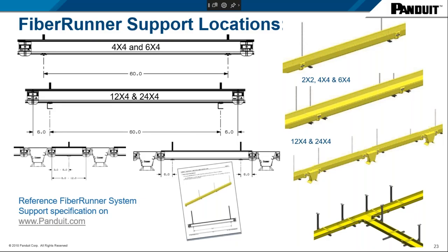And when you have a joiner, such as what we're calling our coupler, what we're showcasing here, those you should have a bracket within 6 inches. So again, we just want to highlight ways to properly support your channel. And these are definitely recommendations that we're making and to definitely consider. We understand that at times it's not always possible. You might have something in the way, but again, these are just best practices to follow.